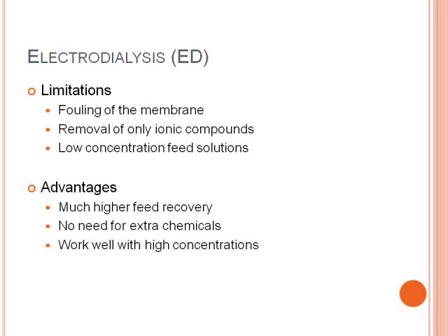Fouling of the membrane can occur. This is when too many species coat the membrane, lowering the ED system's efficiency. Another limitation is that an ED system can remove only lightweight ionic compounds. Also, low-concentrated feed solutions do not filter well with an ED system.